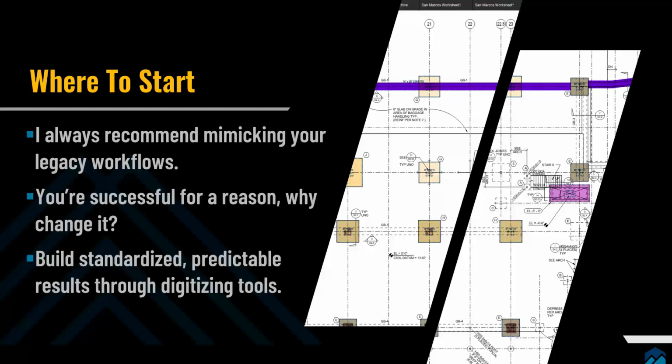Once you have all your custom markup tools created and your spreadsheet ready to go, link to a new drawing. No need to remap each cell, just the source files. Then I would recommend creating a template project folder, subfolders structure to keep all the documents standardized in location as well. Create folders for drawings, spreadsheets, RFIs, site photos, and revisions. This way, on the next project, you simply update the source file to the new drawing folder and start your markups.